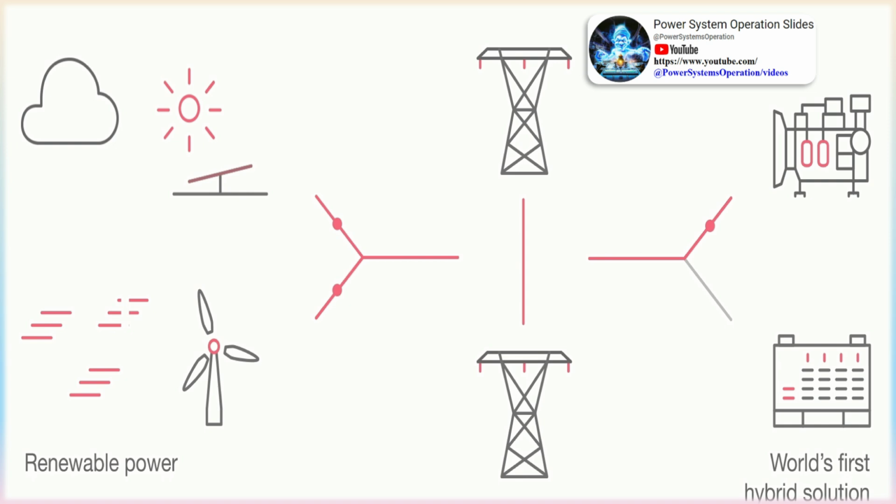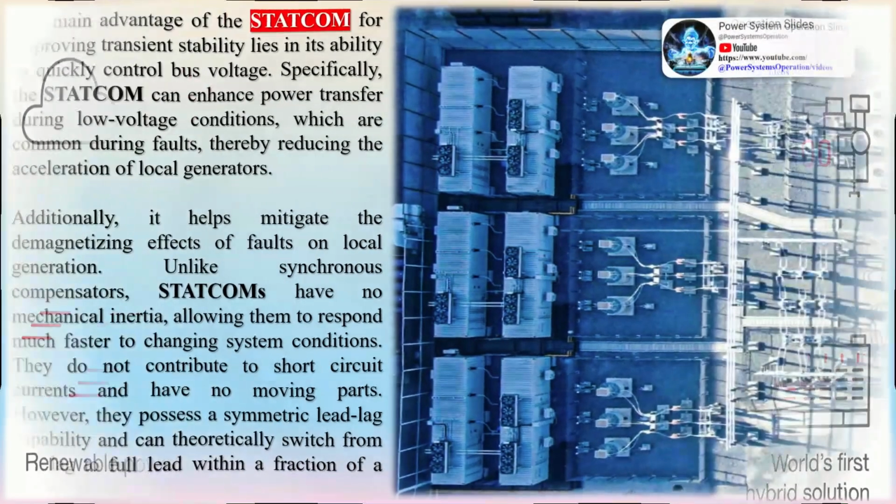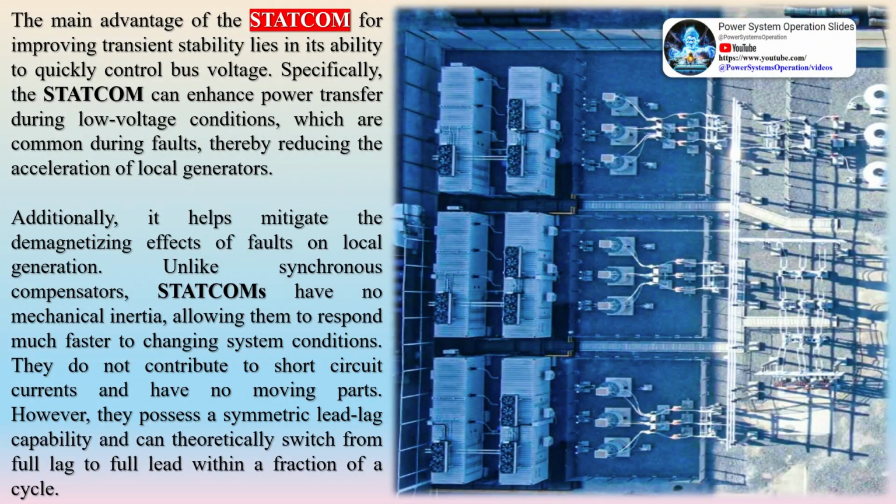Advantages in field of application: modern designs are modular and allow for a high level of scalability and flexibility, ensuring the total required dynamic and steady-state rating. Via the addition of shunt elements, the symmetrical output range of the pure STATCOM device can be adjusted to also meet non-symmetrical performance requirements. For conditions where a fast non-symmetrical dynamic range is required, on the one hand, thyristor-switched reactors and capacitors can be operated in parallel to form hybrid solutions.